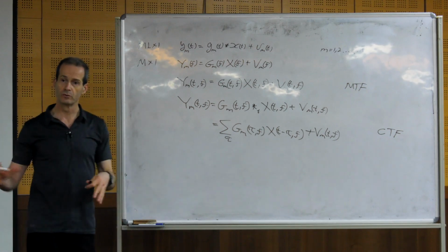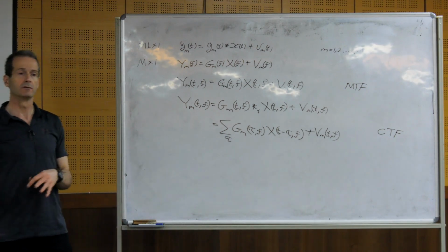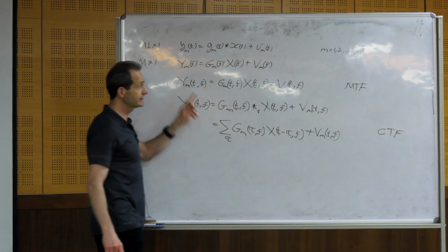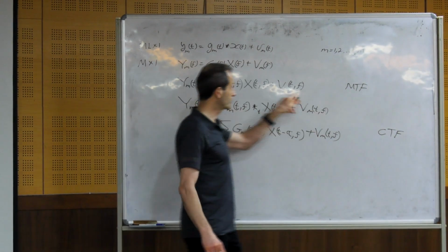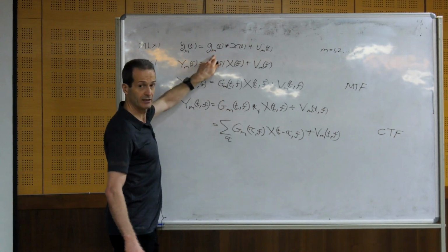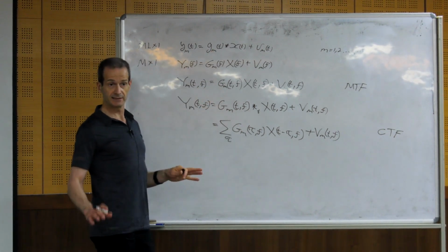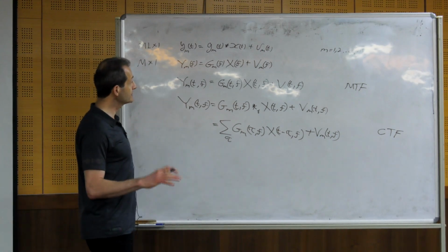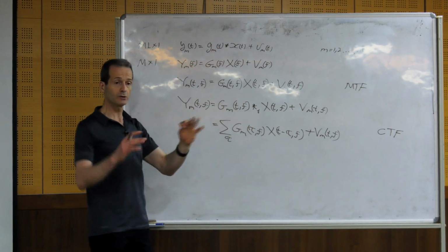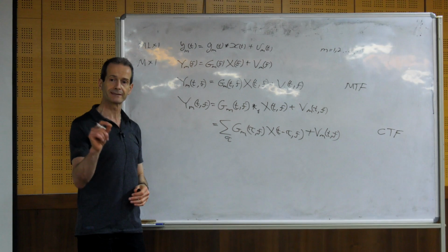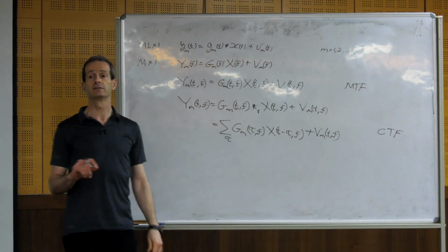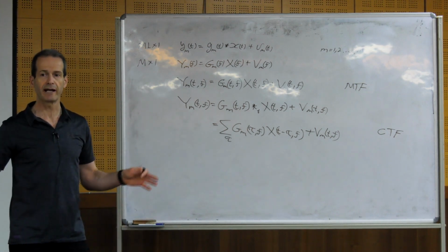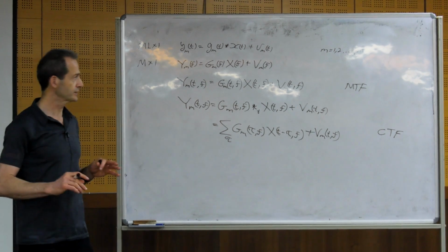And when we talked about the extension or implementation in the STFT domain, if we use the MTF approximation, the multiplicative transfer function approximation, this is an approximation of this model. Generally, it's not correct mathematically. It's an approximation which can be satisfied when the impulse response is short compared to the window, so we have just a few reflections and not much reverberation.